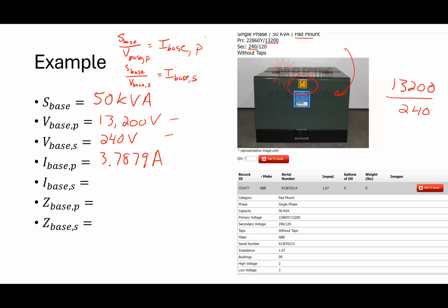All right. So if I have high current, why does high current bother you if you're going down a long distance? Heat, right? I squared R, right? At some point, I got to get the voltage down to a safe number. So I get it down to a safe number once I'm down to the level of 9 houses or 5 houses or whatever, right? So in this case, if I do the math, it works out to be 208 amps. Right, something like that. Okay.